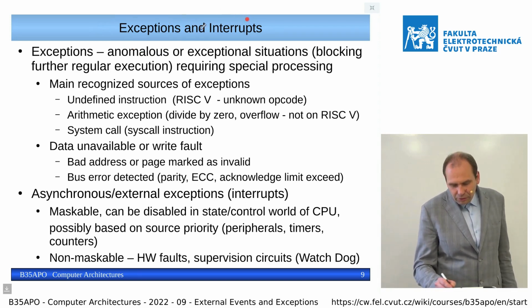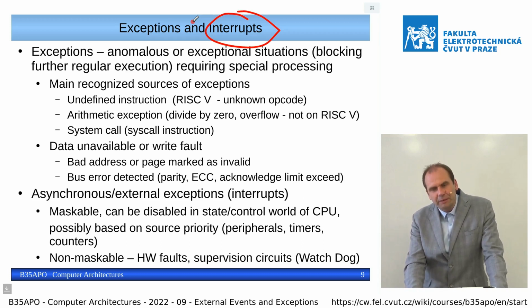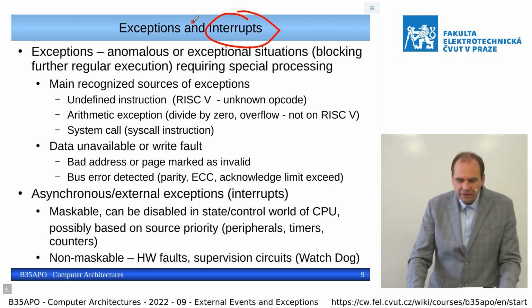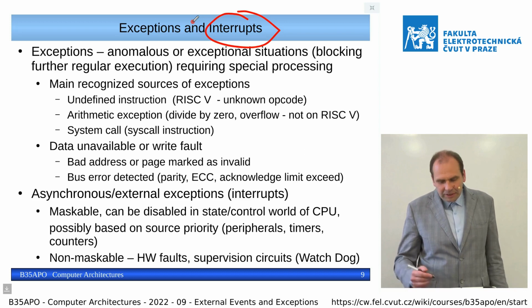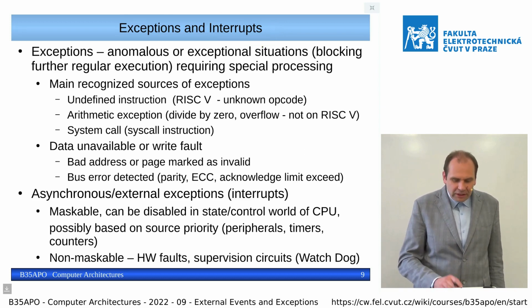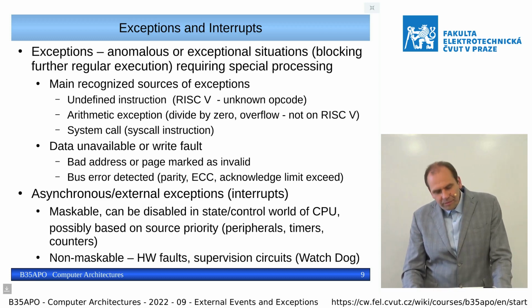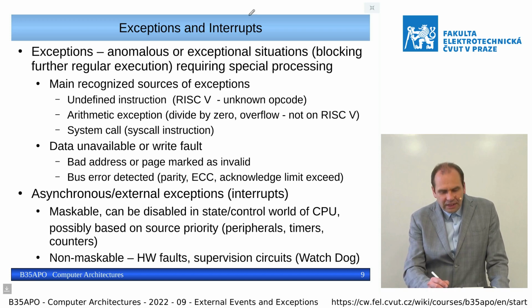Intel uses the term interrupts for both. It uses interrupts for the results of the exceptions caused by instructions, the synchronous ones, and even for the interrupts coming from the outside world. So be careful. Those terms for each producer and each architecture need to be first understood, and then you can map them to the actual sources.